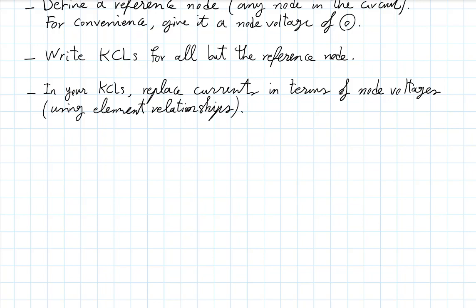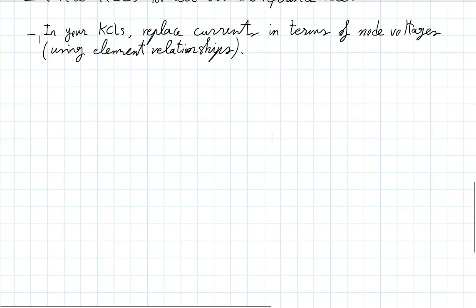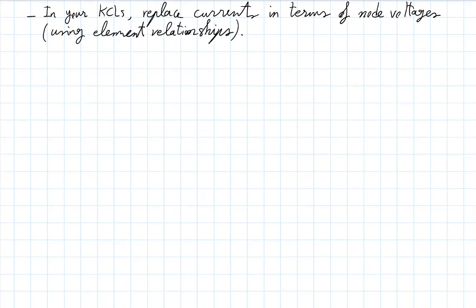And so you might be disturbed by this because then you have this current that's going to linger on in these equations. But there's nothing to worry about because the voltage source gives you an additional relationship between node voltages. So you will have an extra unknown, but then you will also have an extra equation. So anyway, it's better to see this in practice. Maybe I'll put a small note here so that we have it complete, but we'll see it in more detail.